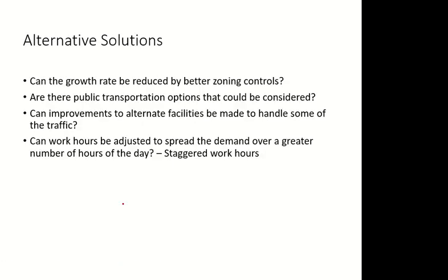So what can you do before the 7th year? What are the options you have as a traffic authority? Some of the options are given here. You can try to reduce the demand of traffic. It is 6% every year, which is very high for an area. So you can control the activities in that area. Commercial activities produce more traffic, so you can control the commercial activities, the licenses for the commercial activity in the area. If you control it, the growth rate will become less.